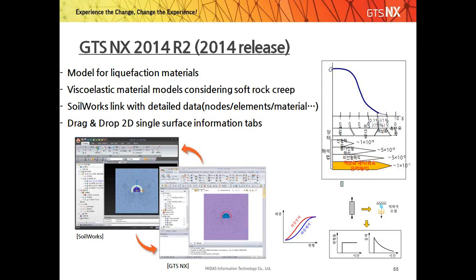What MIDAS GTS supports is the SRM method, that is the strength reduction method, and the SAM method, which is the stress analysis method. I would like to focus a bit on the SAM method. Sir, the SAM method is basically a combination of the SRM method and the LEM method. So what the program does is it combines both.